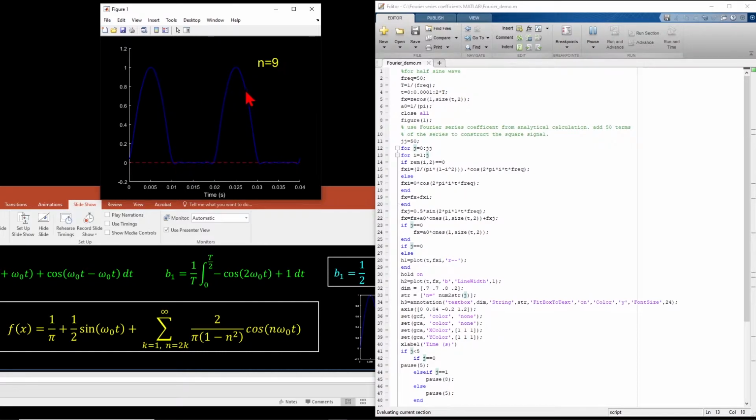And basically for higher n, whenever n is even, we have a cosine term, which adds to the previous summation and gradually shapes the waveform. It's very amazing that using some simple cosine, sine, and DC, combining them, we can get such a type of waveform. It's a much more complex waveform.